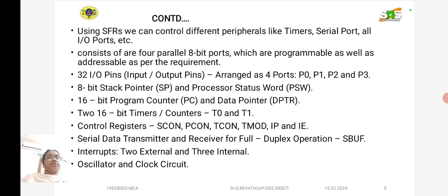SCON is for the serial data transmitter, PCON is power control, TMOD is timer mode, and these are all control registers for instruction execution. It has a serial data transmitter and receiver with full duplex operation, SBUF, and interrupts, 2 external and 3 internal, and it has an oscillator and a clock circuit.